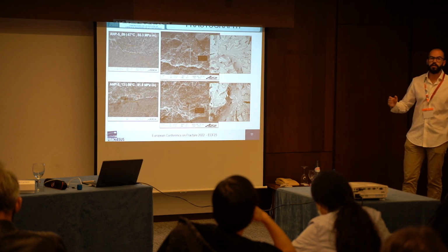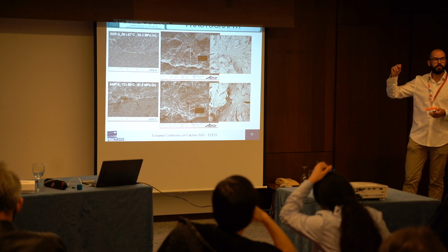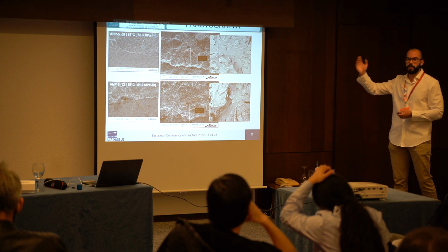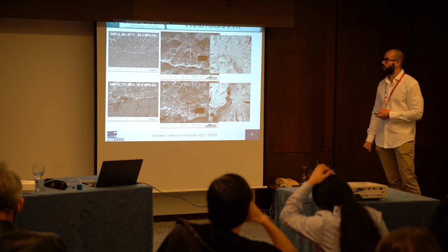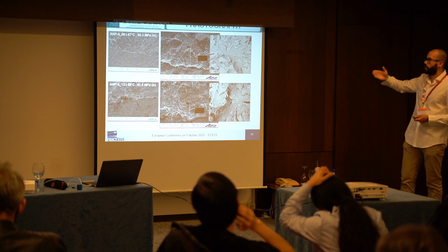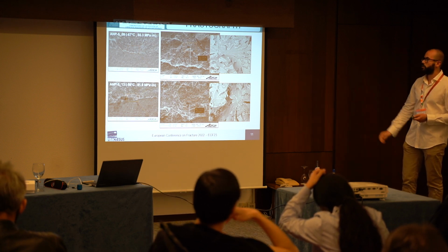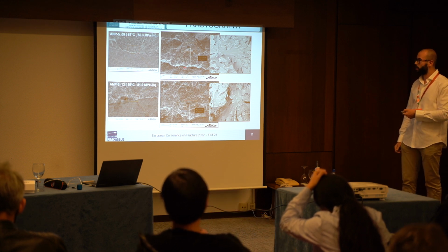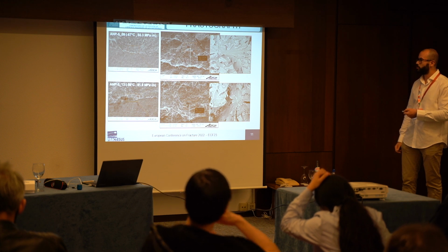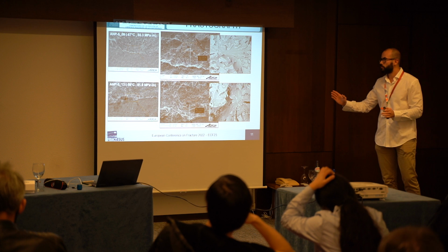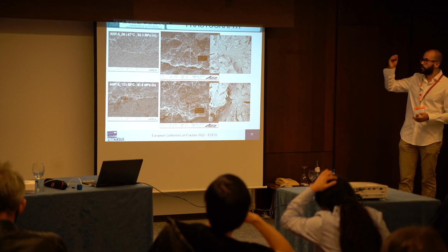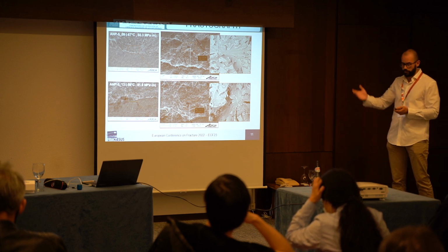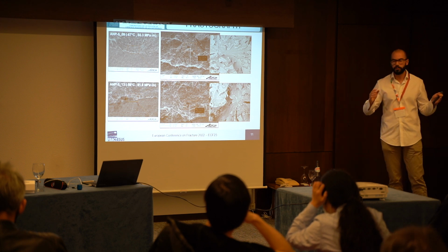Another important thing is to try to localize the initiation sites. Here you have the same example as the other slide. The initiation sites are relatively close to the initial crack, and here you have the small area of microvoids I talked about before. In general, we have demonstrated that these mini-CT specimens are fulfilling the weakest link model because we have found only one clear area of initiation.